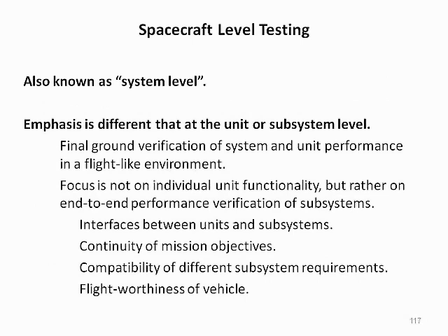Spacecraft level tests, also known as system level tests, have a different emphasis than unit or subsystem tests. At the spacecraft level, emphasis is on final ground verification of the system and unit performance in a flight-like environment. The focus is not on individual unit functionality, but rather on end-to-end performance verification of subsystems. Interfaces between units and subsystems, the continuity of mission objectives, compatibility of different subsystem requirements, and overall flight worthiness of vehicles are demonstrated.